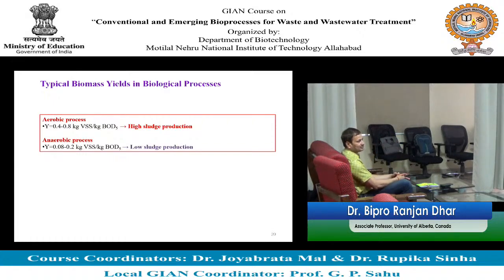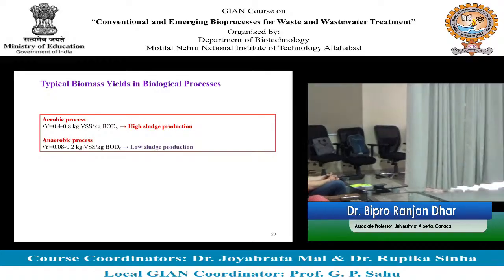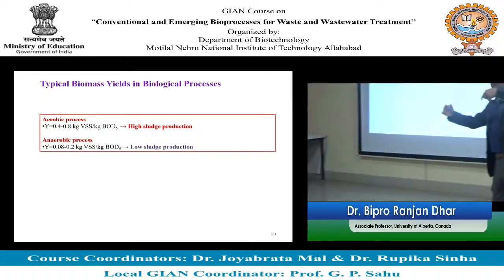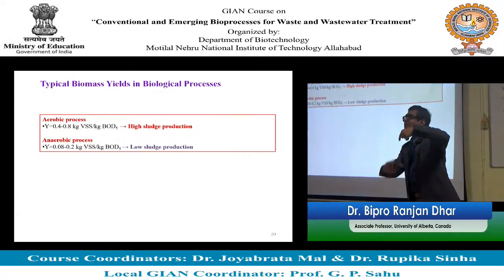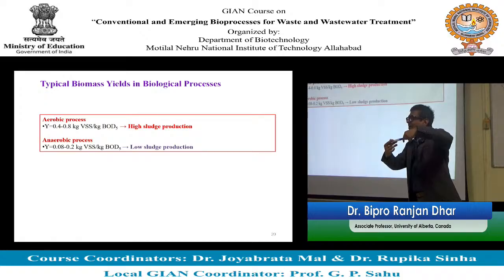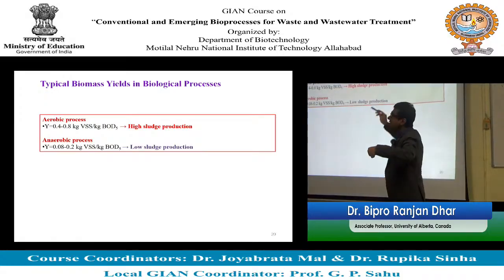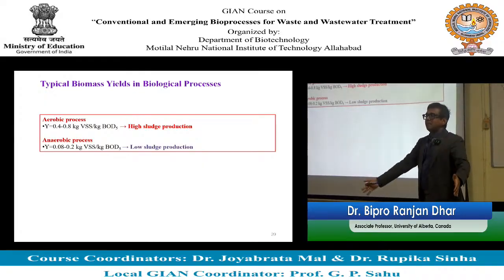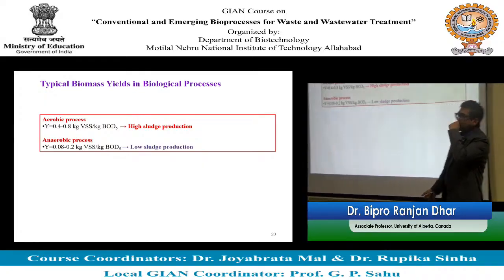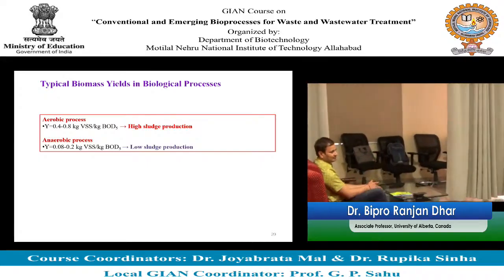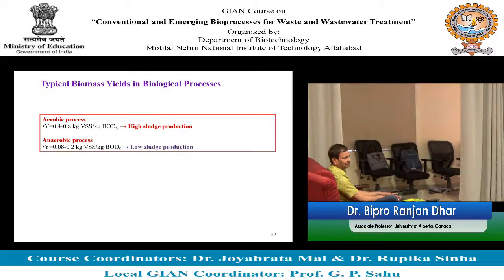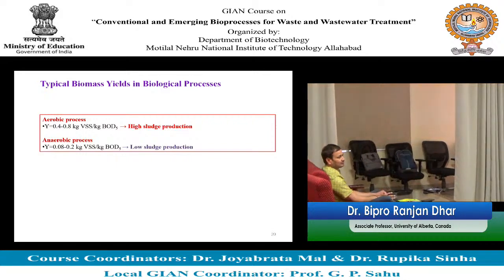In wastewater engineering, yes, there might be some VSS coming from the wastewater, but we consider that as organics. It's a part of my BOD, so I don't consider that as my microbes. Here VSS, I consider as my biomass, my microbes. That substrate is eaten by the microbes, and that VSS can be consumed by microbes, but after hydrolysis, okay.